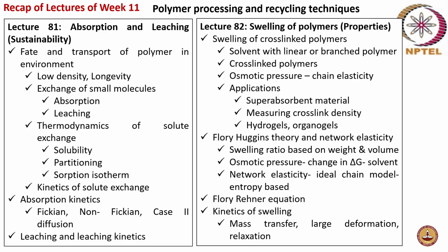And how the exchange of small molecules, for example, a small molecule getting absorbed by the polymer and getting leached out of the polymer, both play a significant role. And the thermodynamics of solute exchange, like solubility, partitioning, and sorption isotherm, and the kinetics of solute exchange, all play a significant role in absorption and leaching for polymers. And absorption kinetics, the different kinds of kinetics it follows, like Fickian, non-Fickian, and case 2 diffusion, were discussed. This was followed by leaching and leaching kinetics.